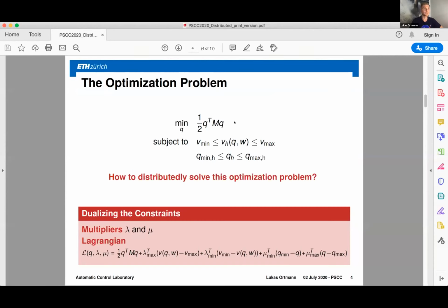On the dynamic stability guarantees, we are going to assume that every time we set a set point, the system is going to converge to its new steady state very fast with all the dynamics in there, which are probably only going to take a few milliseconds. And because we're only actuating every second, or in our experimental setup, we were actually only able to actuate every 10 seconds, but that's not due to the algorithm, but due to the hardware, within that time everything converged, and therefore we won't have any dynamic or steady state stability issues.